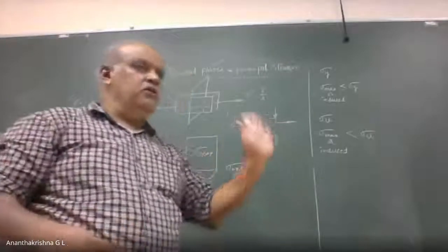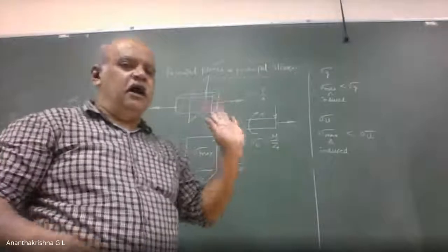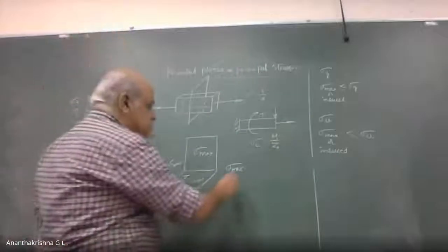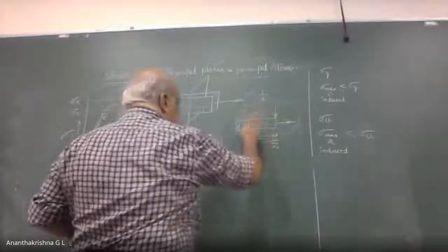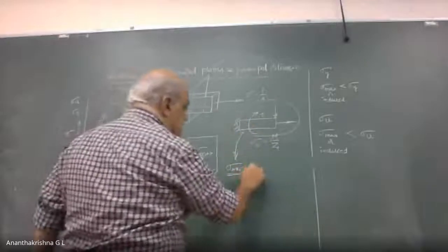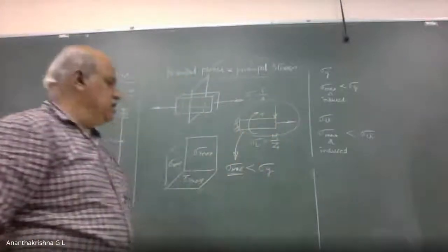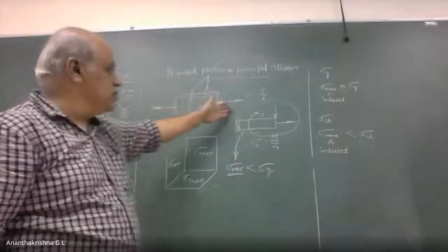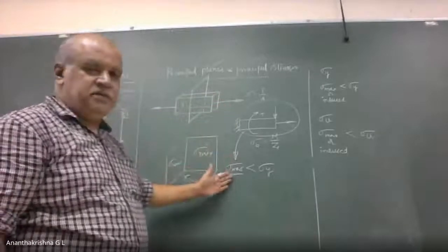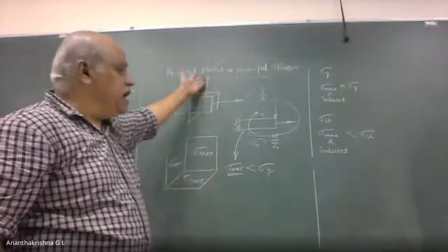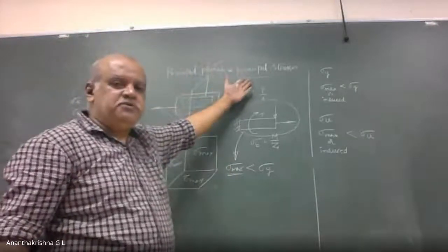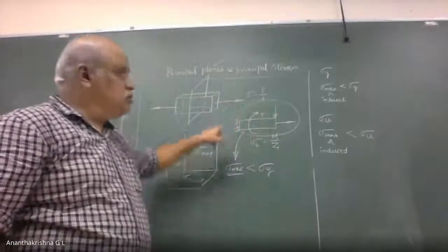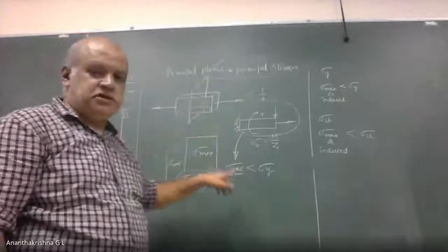It is our job to find out the orientation of such principal planes and on which the maximum principal stress is going to act. So this maximum stress, because of combined loading, should be less than yield stress in case of ductile materials for the design to be safe. If I just take a normal plane, that is a plane perpendicular to the axis, I will not get the maximum stress. So I have to find out planes which will give us the maximum stress induced because of combined loading on the component. Those stresses are called principal stresses.